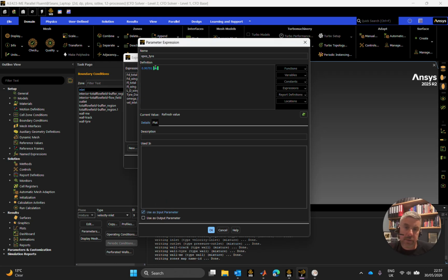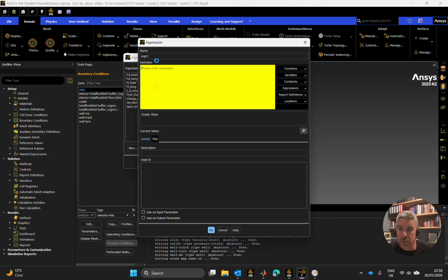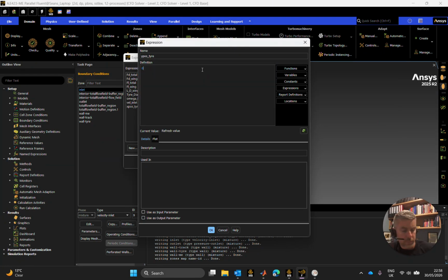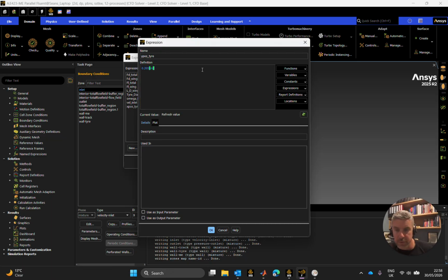And then after this, I'm going to assign the geometry specified X dimension, leading edge to the front of the tire, to drive this one. X position tire, Control C. Let's make sure that's good, 0.907 meters, okay. And then we also need new Y position tire. And that one was hub height, 0.205, specify that in meters, and use that as an input as well.